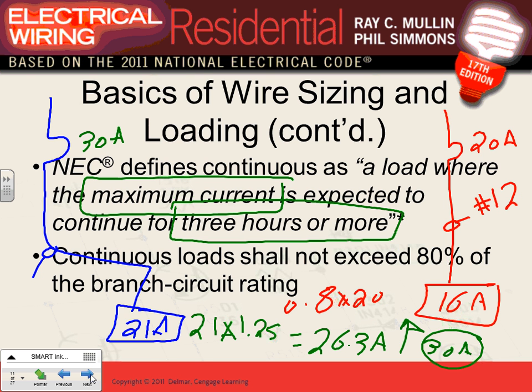Now, I need to size the cable, right? You size the cable again at 26.3 amps. Can you guys go to 310.15(B)(16) and find me a conductor that can carry this? I know this will be page 154. Can you give me a conductor that can carry 26.3?